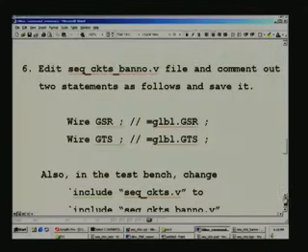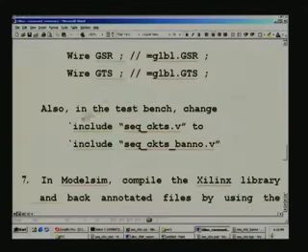The next step is, in addition to this, you have to go to the test bench and then change. We had used .vm for that earlier, you remember, for that synthesis. Instead of .vm, it should be this back annotated file. So it is exactly the same thing we are going to do here, and again after this run the ModelSim. That is the next step here.